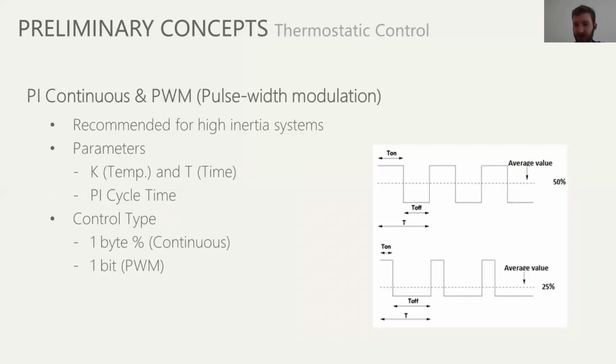Say, for example, on the floor heating from off to on. So if the system is turned off and then you turn it on, you might define that temperature difference in a given time somewhere around 5 degrees in 4 hours. And that's not to be followed blindly. That's not just 5 degrees in 4 hours always. That's just a reference value. Of course, it depends on the system. It depends on the temperature you are producing hot water for the underfloor heating, for example. It depends on quite a lot of parameters you want to check in your own installation.